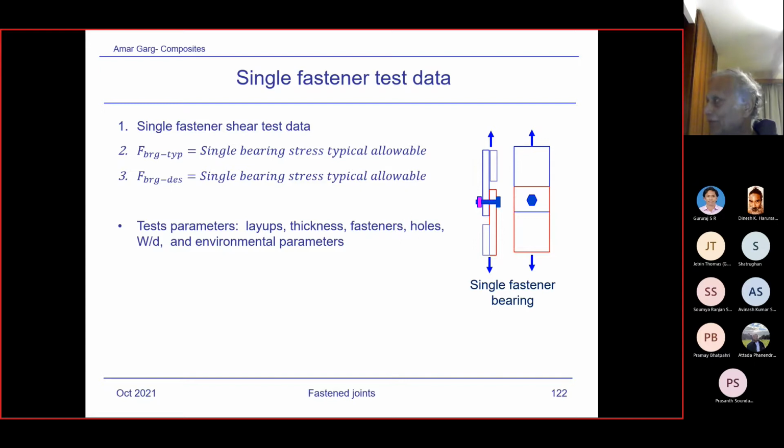And sometimes you get a lot of surprises. FEM is showing, and that's where the trick comes. FEM sometimes gives surprises. Stress concentrations. It predicts very high load. Then we are investigating. Oh, this is very high load. Why is it so high? And suddenly at the next element, there is a significant drop, which may not really happen in practice. That is another thing. Sometimes you get surprises.